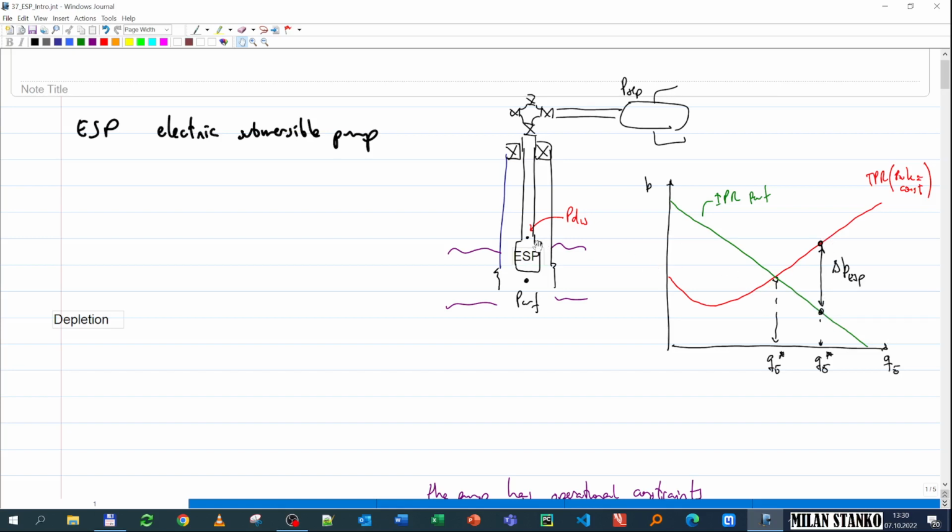Of course, the ESP is not only at one point, but actually it might take a few hundred meters. So these curves should be modified. For example, the tubing curve, maybe I should only take 200 meters out or 100 meters out of the length, but essentially it's the same result. I just try to make it in a point, concentrated in a point, just that it will be easier to explain.